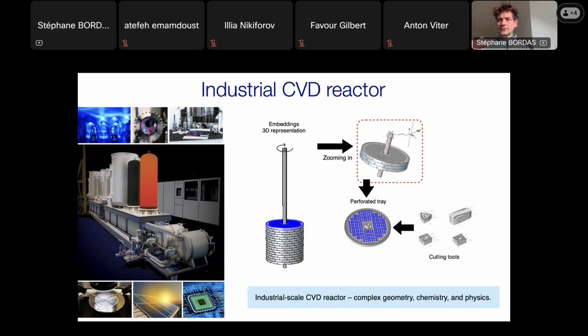You really want to have a very flat surface such that when you use the tool, you do not create large stresses. You can imagine if you have a wavy surface, you try to press, the stresses will be much higher than if you have a flat surface. Upon a flat surface, well, the stresses will be equally distributed and you won't have localization of stresses. So that's the key question. How do I make a surface which is flat enough? And why is that useful?